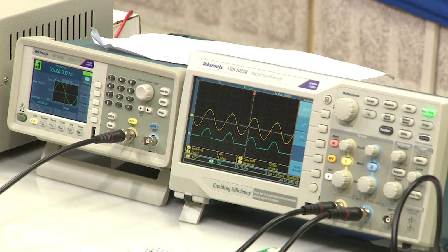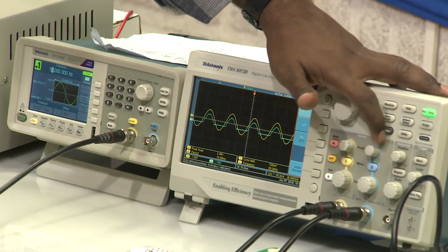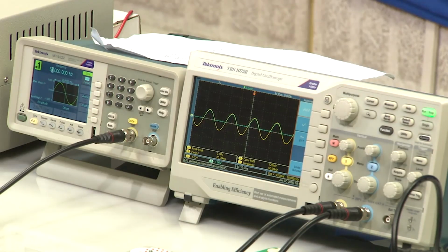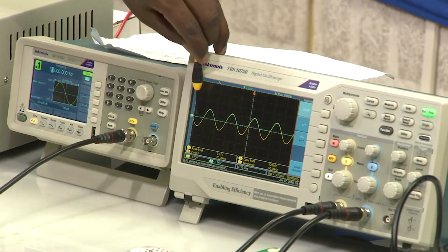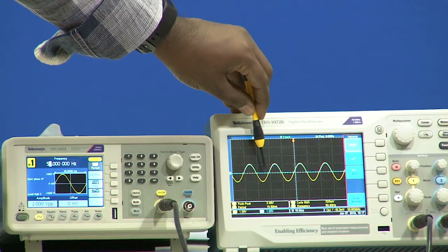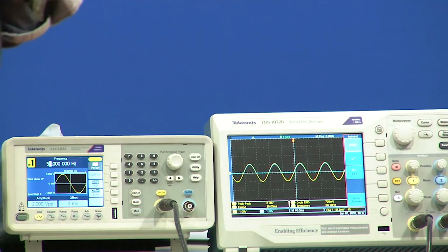The reason is that we have to find out only the positive peak, we do not need negative signal processing in this case. That is the reason we are going with the removal of the negative signal. Now, if I observe, there is no negative signal. Whenever there is a negative signal in the input, the output is 0, and when there is a positive signal it passes through, and the output is 0 again when there is a negative. So it is completely removing the negative peak of our signals.